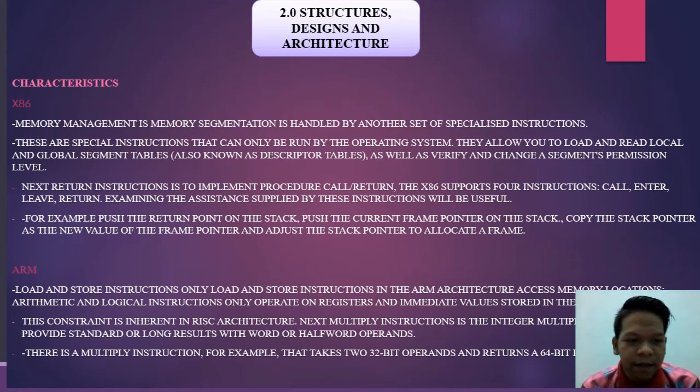Lastly, load and store instructions. Only load and store instructions in the ARM architecture access memory locations. Arithmetic and logical instructions only operate on registers and an immediate value stored in the instruction. This constraint is inherent in RISC architecture.